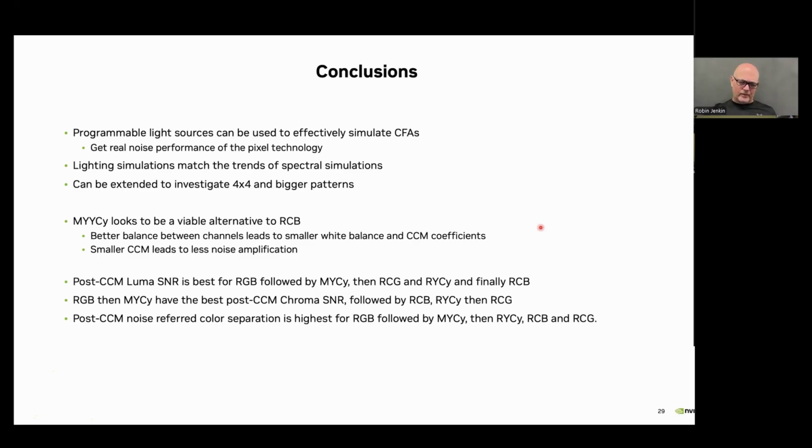So one of the things that I haven't published yet is looking at combining something like a 4.2 micron clear channel sensor with what's currently used for the forward-looking cameras, which we seem to have settled on, the 8.4 megapixel 2.1 micron, as a node.